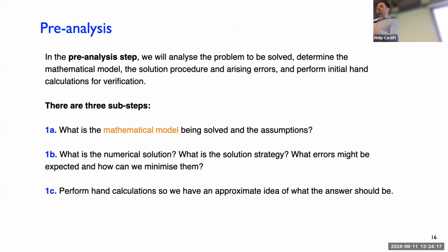Because these are complex software packages, you rarely will just run an analysis and assume it's correct. You'll have to verify in some way that it's correct. You might use some simple hand calculation, or check what other people did. Maybe there are solutions in the literature or online that are semi-relevant, and you can check whether this is the right order of magnitude, because it's very easy to get wrong answers.